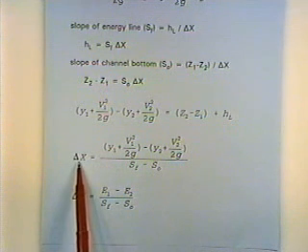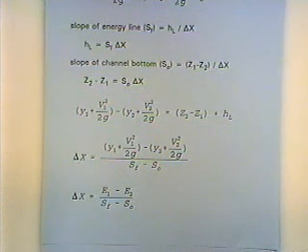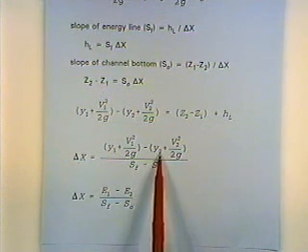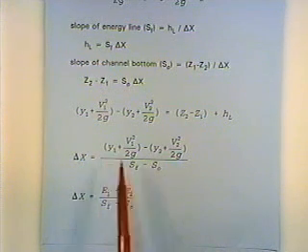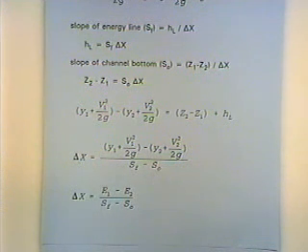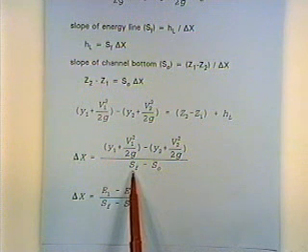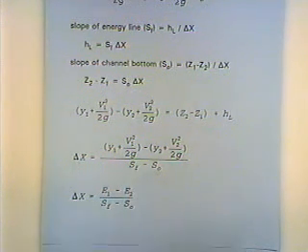We'll compute the horizontal distance between the 10-foot and the 9-foot depth. Then we'll do it all over again. We'll plug in 9 feet for Y2, 8 feet for Y1, and just keep plugging into this equation over and over again. And of course we'll have the friction slope term, and we'll be using Manning's equation to solve for that.